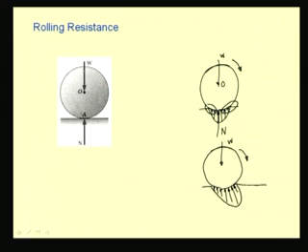So, we see that if we take the resultant of all these forces, now it will no longer be this vertical force N, but rather a force which acts at some distance away from the original point under consideration below, say O. So, now this reaction force, still passing through O, but having a displacement in the direction in which the wheel tends to roll.